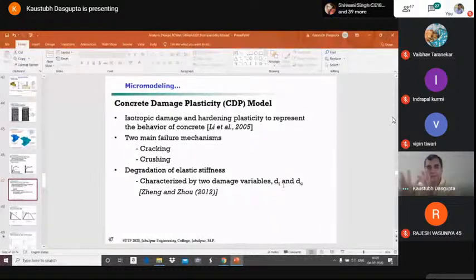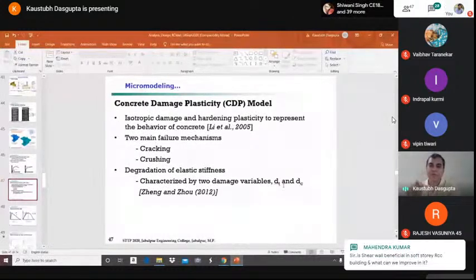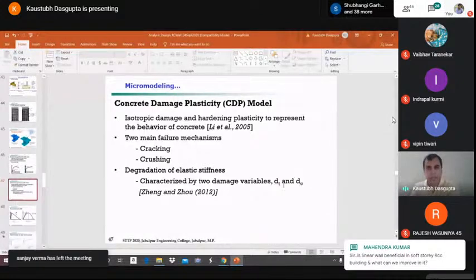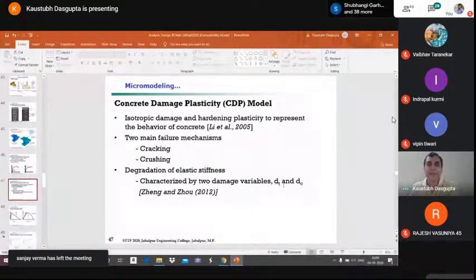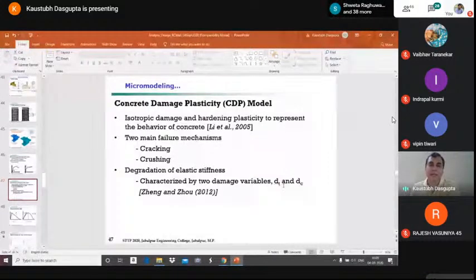So you have the numerical model. You start off with some values of these parameters. Along with these damage parameters, there are other parameters also in CTP. So you start off with certain values, then try to match the stress distribution, the observed peak lateral strength, lateral deformation, the load deformation curve, different characteristics. You try to match with the original result. That may be an experimental result, that may be again a validated numerical result.